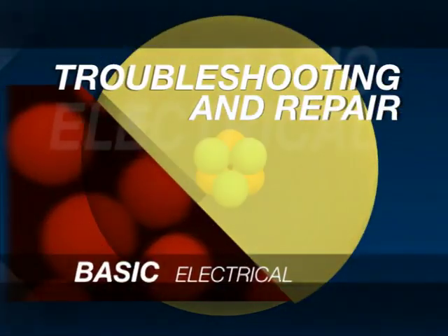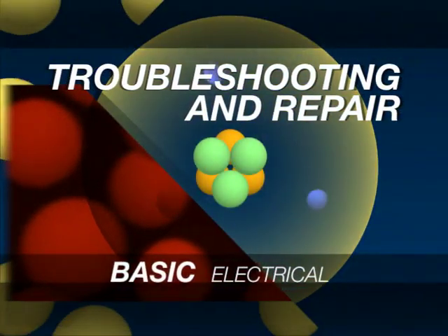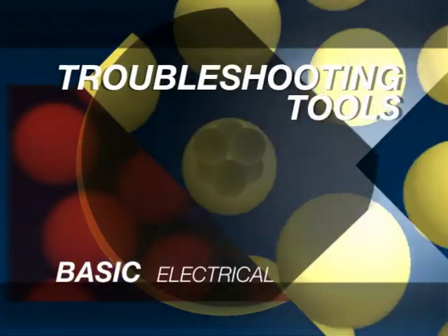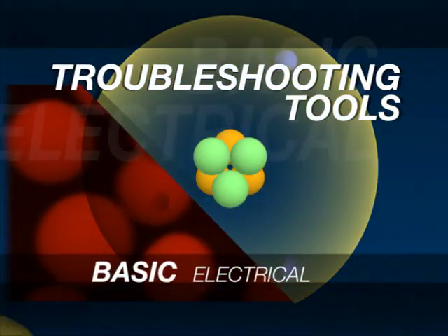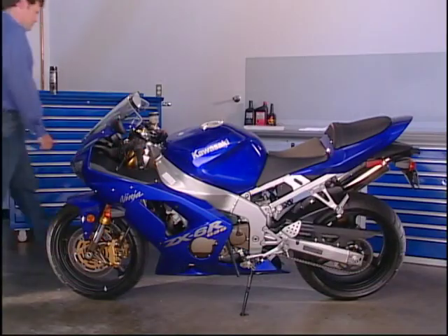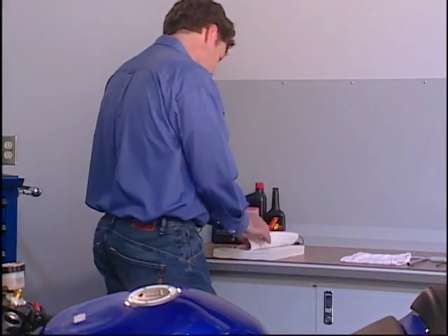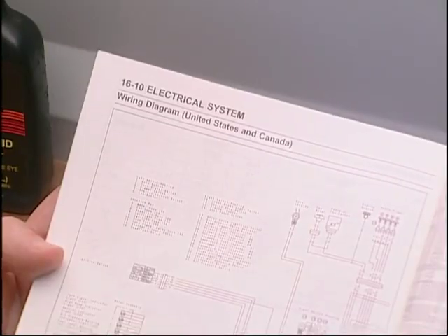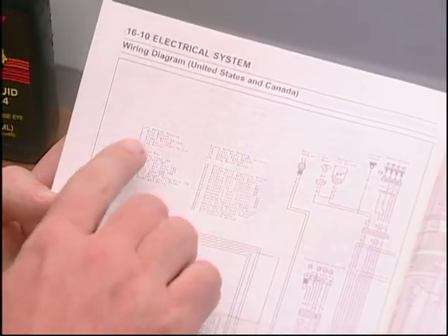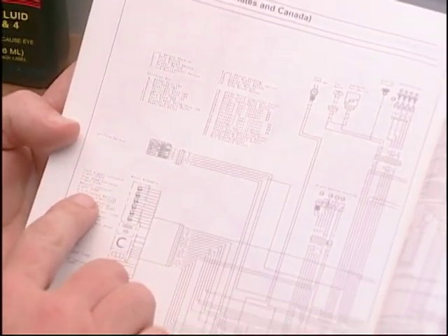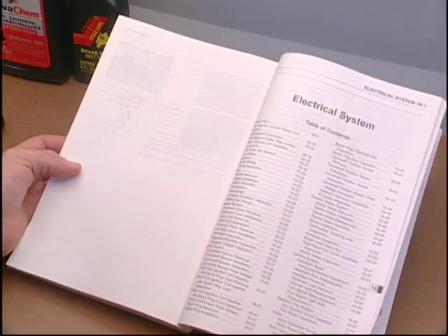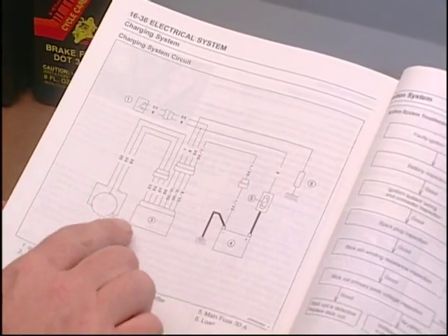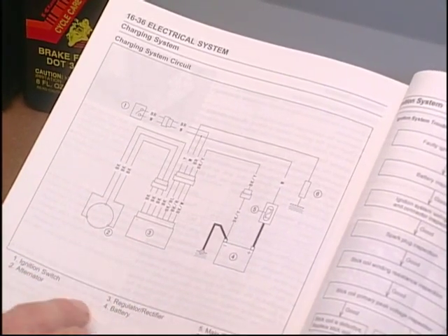Now that we've seen what electricity is and how it gets to where it's needed, let's look at how to find and repair problems in electrical systems. A few basic tools go a long way when it comes to troubleshooting. One tool that's a must-have is the correct service manual for the year and model vehicle you're working on. The wiring diagrams, testing procedures, and component specifications contained inside the manual are invaluable. In addition, most service manuals have wiring diagrams of individual electrical systems to help simplify the diagnostic process.